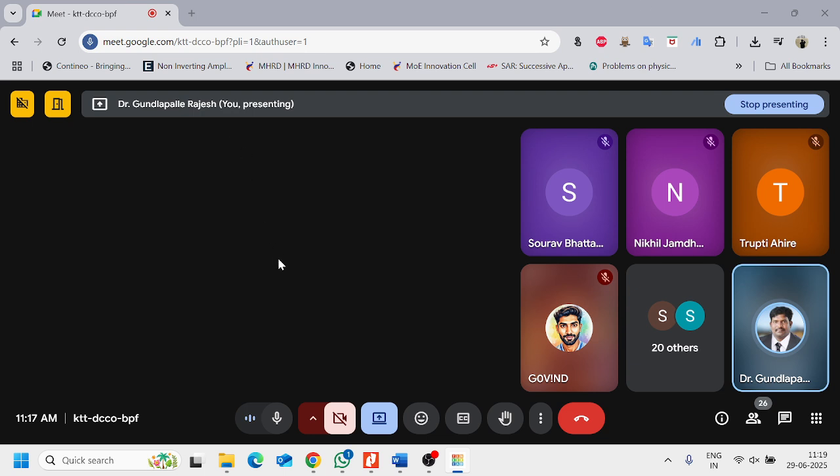See, two things I have not done. First one was connecting your push button through 5 volts. This one was missing in the earlier case. So these two connections I have not used. One we are directly connecting to the negative terminal, so this I'll connect to the ground.